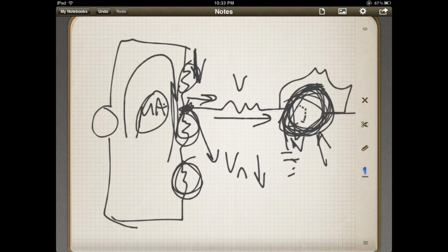Okay, this was a big misnomer that I've seen lots of engineers struggle with. I even struggled with it when I first got into all this analog stuff, because it's stuff that you're never really told. You're always told that, hey, these amplifiers, their internal impedance, this current here, this I input, is equal to 0. Well, no, it's not equal to 0. So you got to look at the data sheet and see what it is.